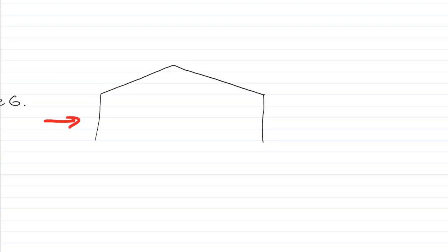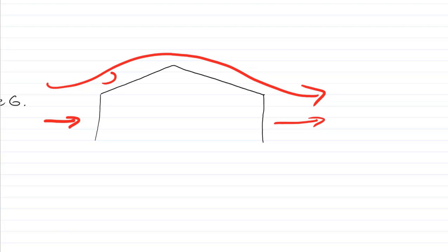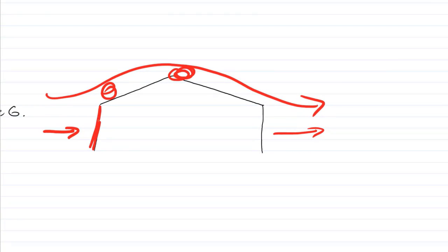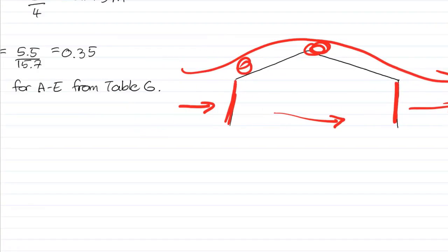If you've got the wind blowing from one side, going over the building, and then suction on the other side, there are constant fluctuations, and this can lead, on wide flat buildings, to the maximum pressure on one side not occurring at the exact same time as the maximum pressure on the other side. So this lack of correlation is accounted for by reducing the total resultant force from one side to another. It's the horizontal net lateral force that is reduced by applying a factor.